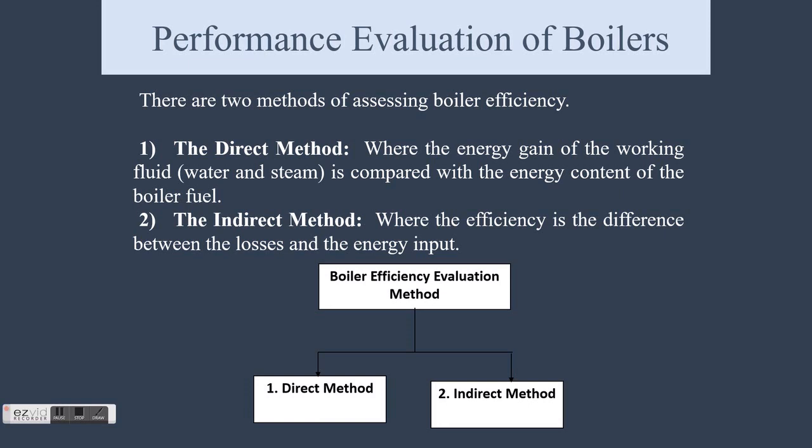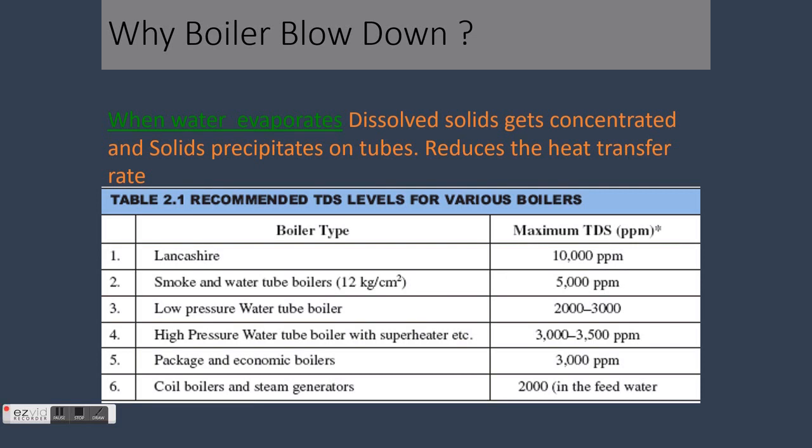Next topic is boiler blowdown. When water is boiled and steam is generated, any dissolved solids contained in the water remain in the boiler. If more solids are put in with the feed water, they will concentrate and may eventually reach a level where their solubility in the water is exceeded and they deposit from the solution. Above a certain level of concentration, these solids encourage foaming and cause carryover of water into the steam. The deposits also lead to scale formation inside the boiler, resulting in localized overheating and finally causing boiler tube failure.